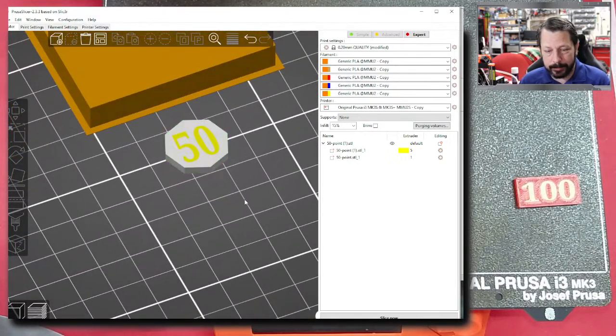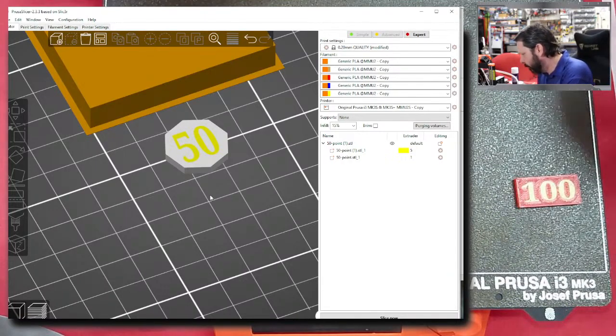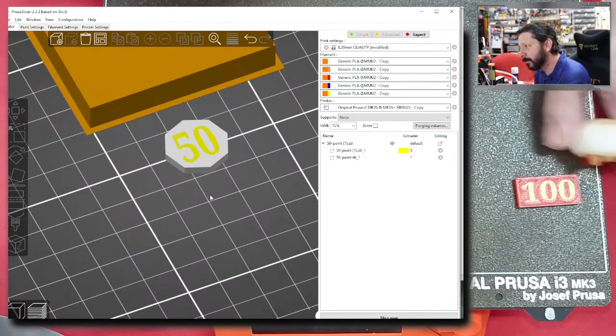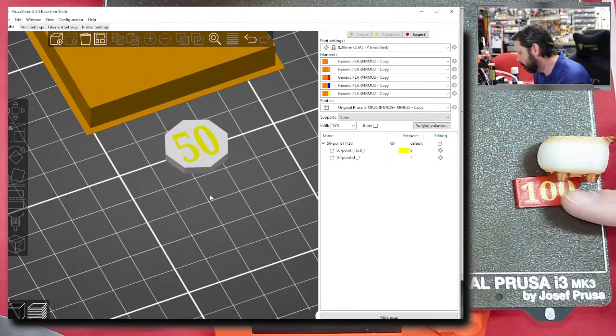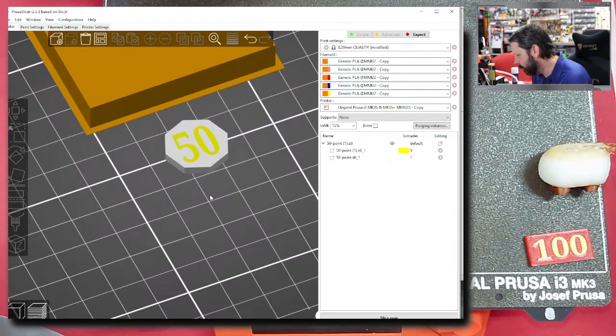The problem with my white filament is that it's very milky, so it's not translucent exactly, but it's enough that it doesn't purge very well. So the default amount of purge tower doesn't actually get all the other color out of it, so it gets tainted. Oh, you can see that. Where'd I put that part? I did print one other part. I did print part of this, but it came loose. That's why I started with the hairspray. It's because I was getting parts come loose.